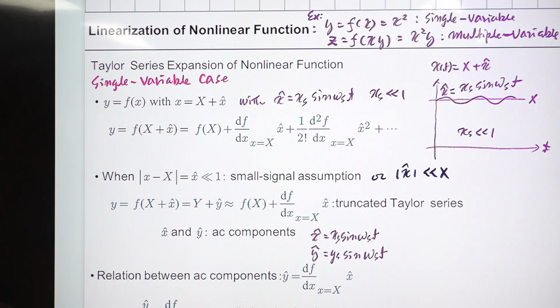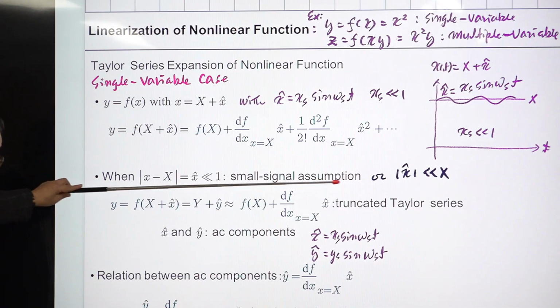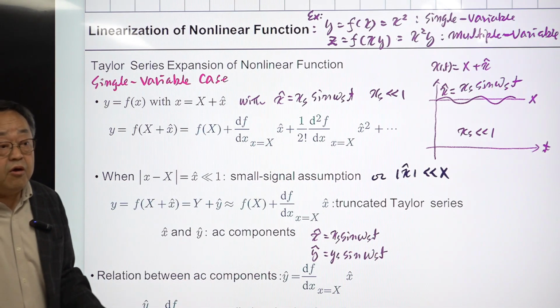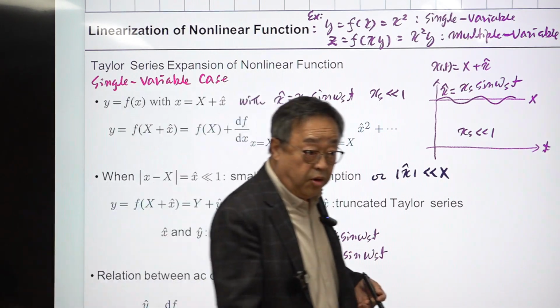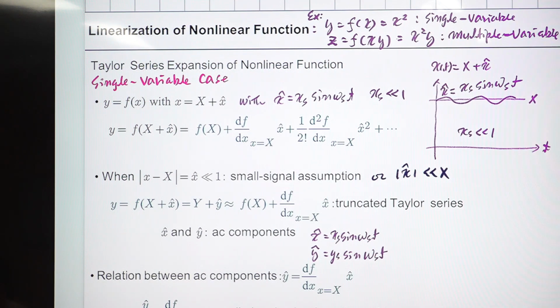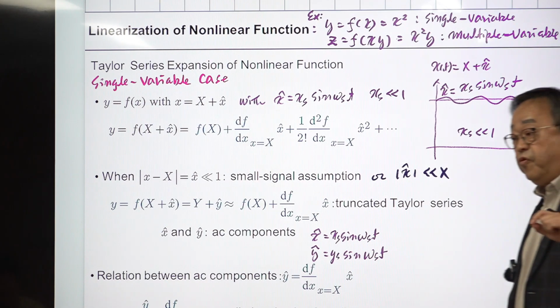Okay, so this is the same expression. It's called the small signal assumption. I said this assumption is all around us when we are talking about the PWM converter. Without that assumption, you cannot do anything. Okay, maybe we need to use some technique for nonlinear systems, which is useless. Okay, it provides something, but the result is so complex and gives no insight on the dynamics and absolutely no information about the design.